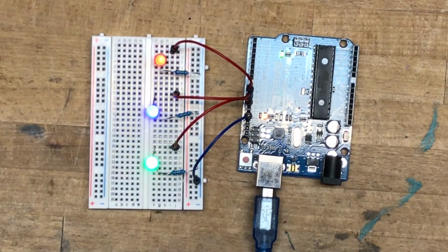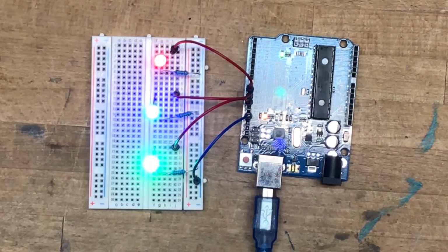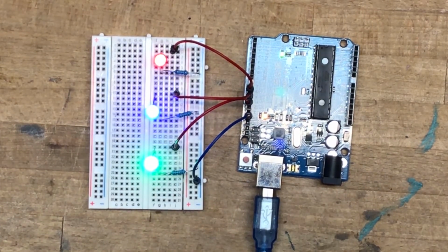So here's the circuit for the next bit of code we'll be working for. It's essentially identical to the last circuit from last week, again, except we're using pins 9, 10, and 11. And it's identical to the last piece of code for the single LED, but now we're using 3. And this can be as many of these as you have digital pins with the tilde sign next to them that can emulate analog signals. So this is 3 LEDs emulating 3 separate analog signals and fading in and out together. Let's go check out the code.